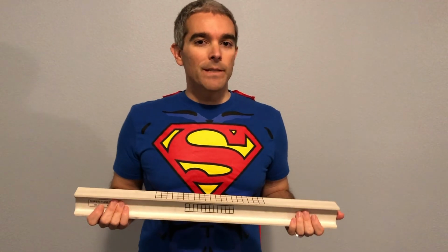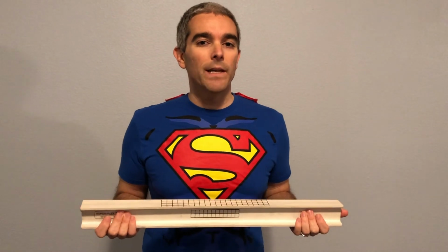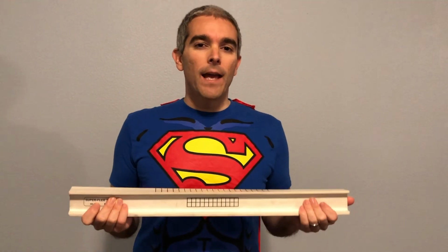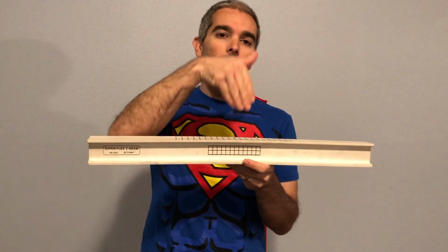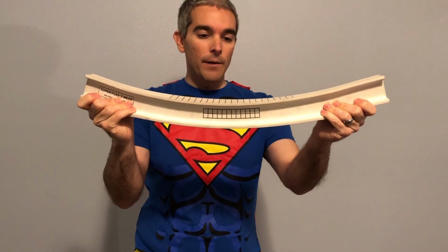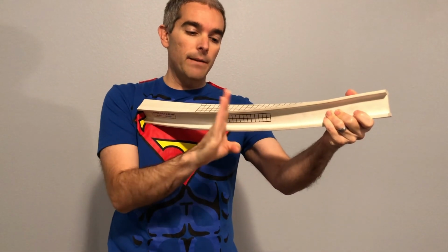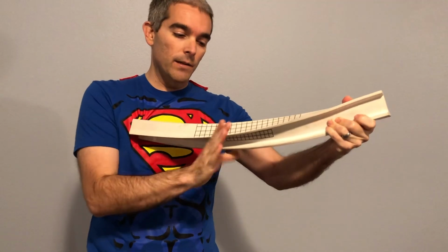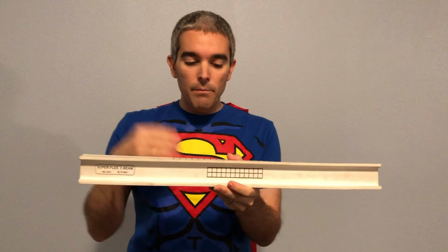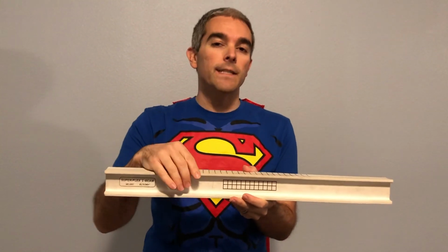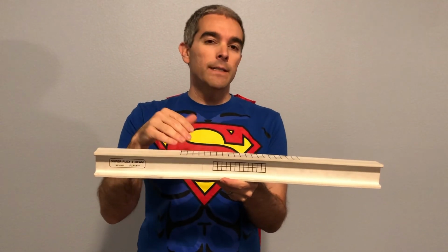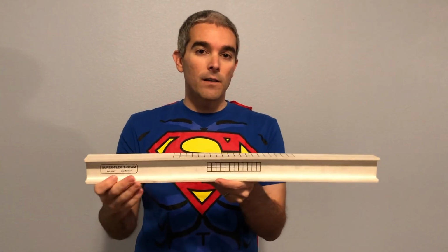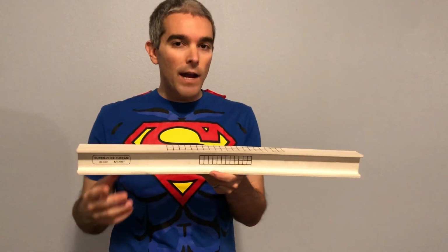We said one of the problems with shear stresses is that they can lead to warping in the cross-section. So what is warping? Warping happens when plane sections no longer remain plane. When we have loads that are applied through the center of gravity of the cross-section, then the beam will bend downward and we'll have nice plane sections remain plane, and even though they're bent, the cross-section is still one plane. The problem is if the shearing force is not through the center of gravity, or if you have an unsymmetric section. What that can lead to is non-uniform shear stresses causing movement in the longitudinal direction in your cross-section.